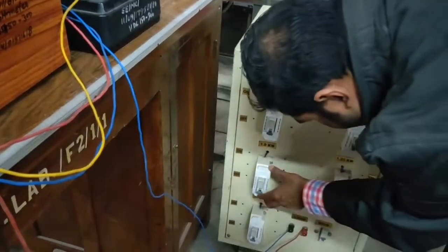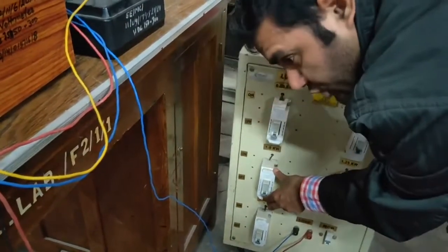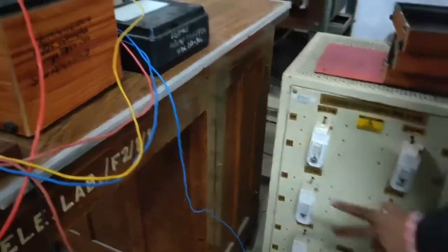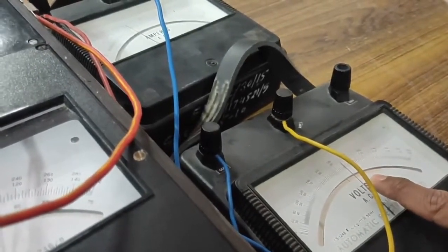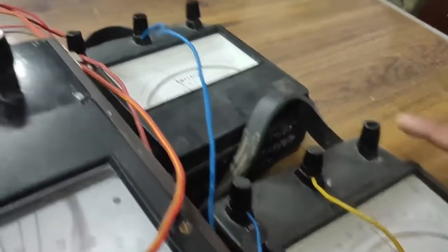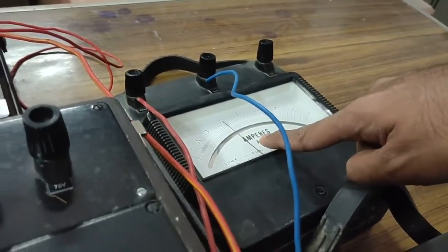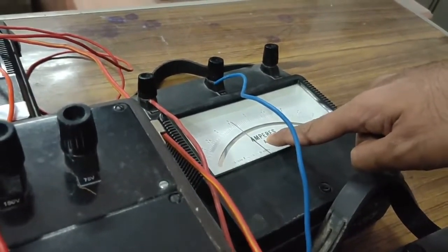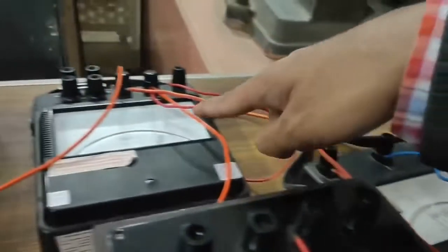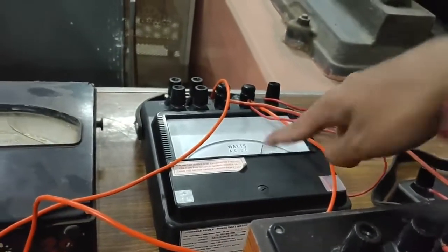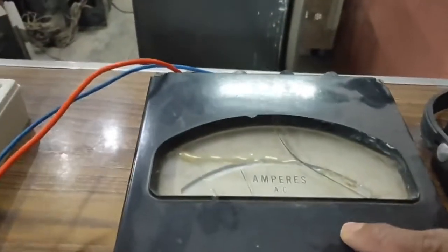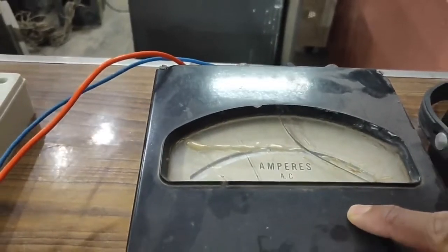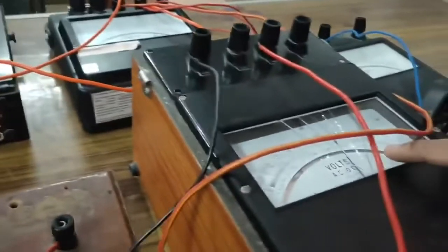So the applied load right now is 0.5 kilowatt. Let's apply another load of 1 kilowatt so that the total load becomes 1.5 kilowatt. Again, you have to note down the voltage on the secondary side, which has reduced further. It's around 190 volts. You can measure the current on the secondary side, which is around 5 amps. Similarly, the input power needs to be recorded, the input current too needs to be recorded, and the applied voltage also.